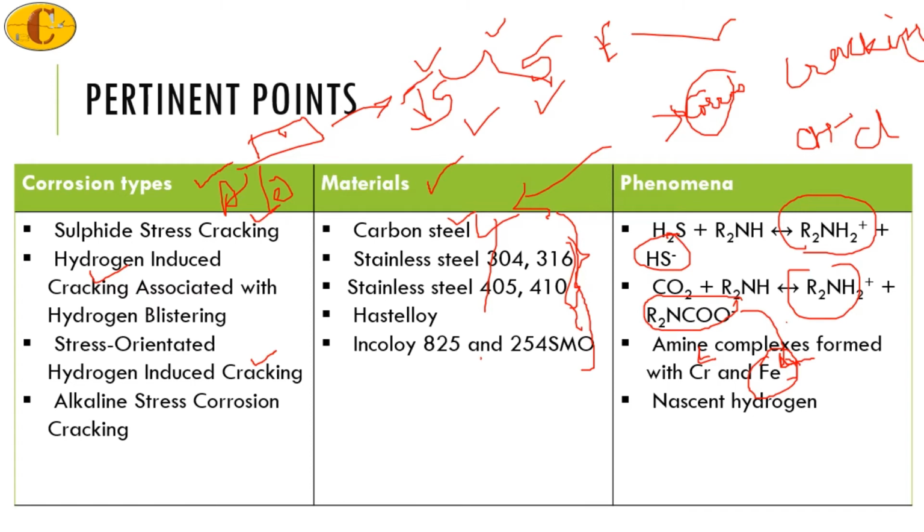In fact, when there is a material loss in both of these cases, you will not have a thick scaling formed immediately. There will be small pits formed first in the substrate, and it is in these pits that the cracking will begin. So when you want to avoid this cracking, you have to consider the environment, and you have to choose the material which is the most resistant to corrosion in the environment.